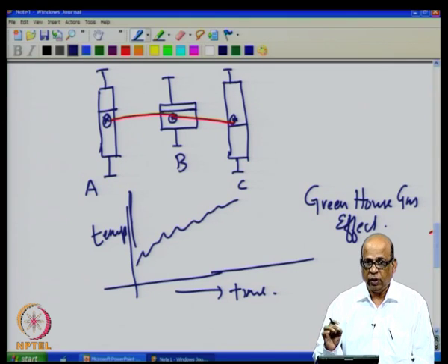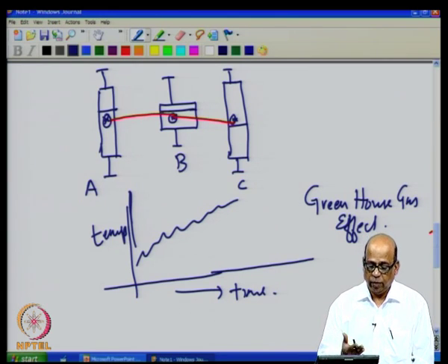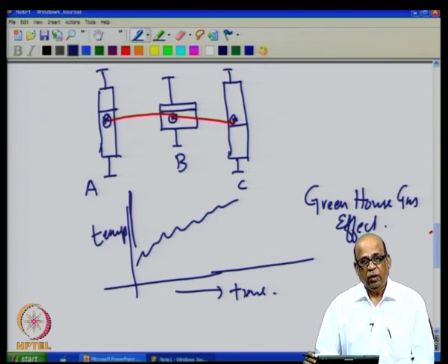As the temperatures change, a direct implication will be on the evapotranspiration. Evapotranspiration may start increasing if all other influencing variables are held constant. Of course, the global average temperatures will also have implications on several other processes, but the direct implication will be on evapotranspiration, and evapotranspiration has implications on the irrigation demands and crop water demands.